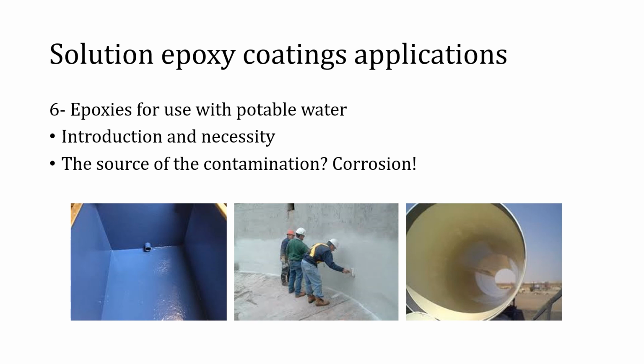In addition to the corrosion and its associated pollution, in concrete tanks of potable water systems, there is a risk of growth of microorganisms and biological matter, which makes the water unusable for human consumption. This indicates that the surfaces in contact with potable water have to be protected. However, normal paints and galvanization fail to serve this purpose. Under such conditions, non-toxic epoxy coatings are the best choice to protect the substrate from corrosion, abrasion, or chemical attack, which consequently prevents the contamination of water.